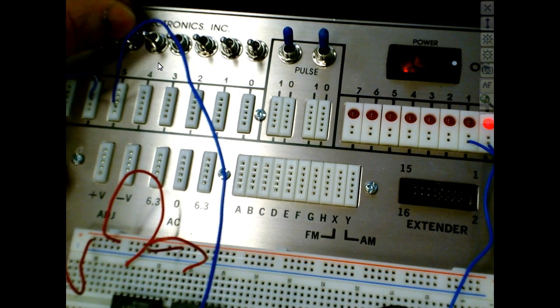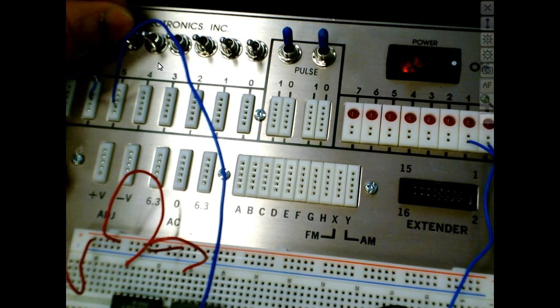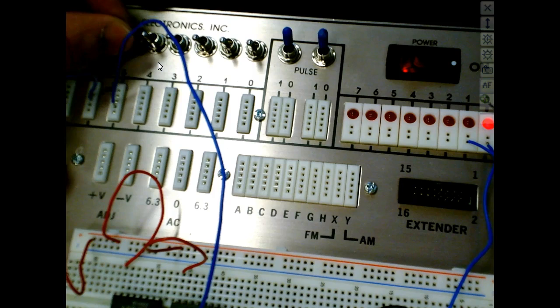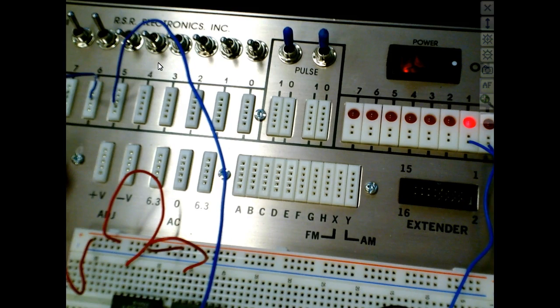Oh, see, so there it came up set, there it came up reset, reset, reset, reset, set, reset, reset, reset, reset, reset, set. So see what I'm talking about? So they call that one the ambiguous state, because when we bring it out of that situation, the latch comes up, we don't know, right? Okay, so you see what we did. What did we do? We added an enable to this, so that would be pretty good for me to have a latch.